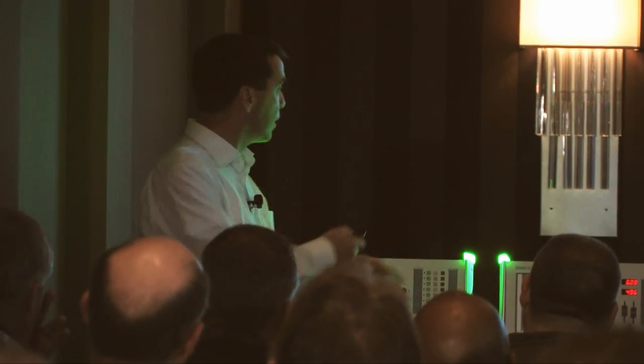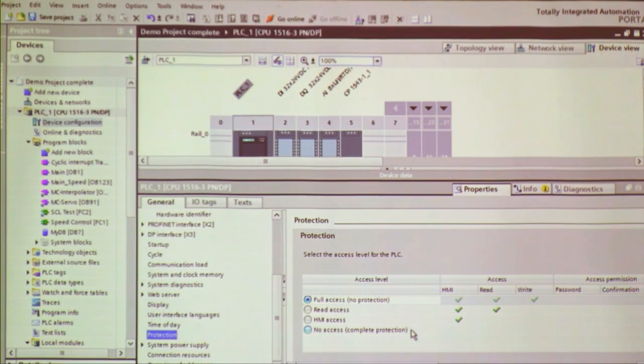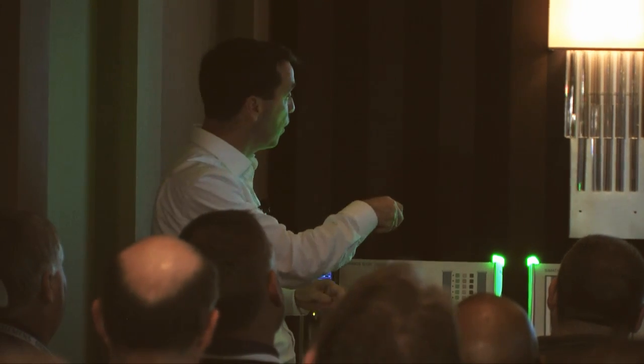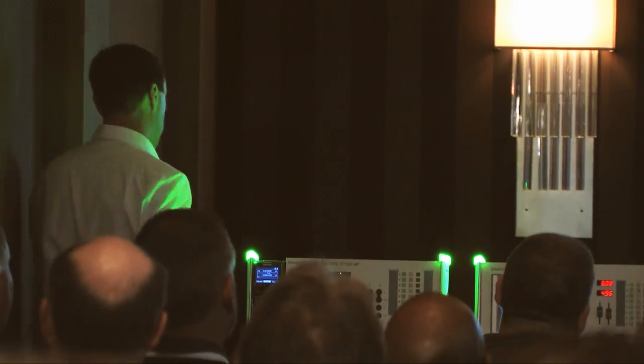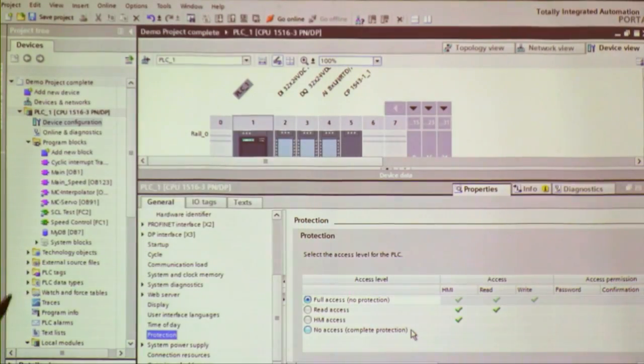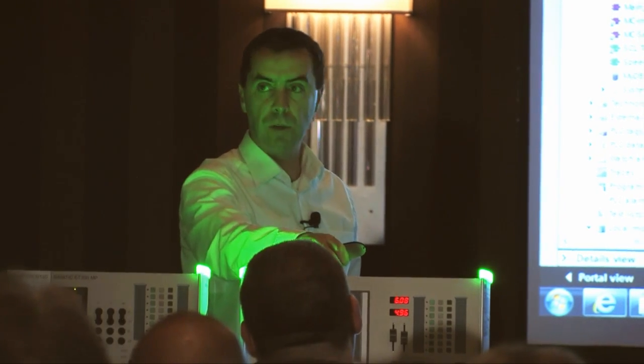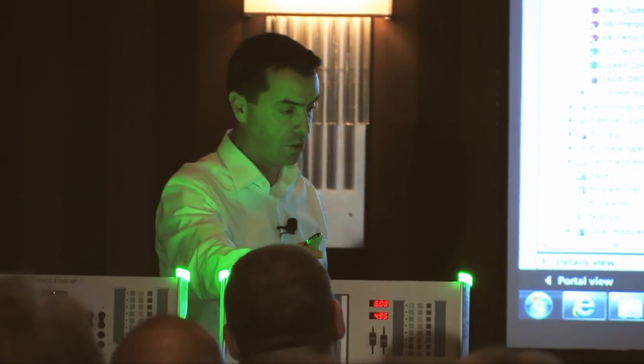All right? So what's new is this fourth level of protection here in regards to access protection. It means not even an HMI can connect and change data to the PLC unless it has a password to do it. And so that feature is only applicable to the newer panels, because only the newer panels in the software have that feature where you would set up that password for those HMI panels if you have this higher level protection access added. Okay? So the last thing, of course, but it's difficult to demonstrate here in software, is the improved manipulation protection against replay attacks and password sniffing that they've added to the ports of the 1500. And we also have communication modules where they have a VPN available, so you can knock yourself out as far as the security is concerned.